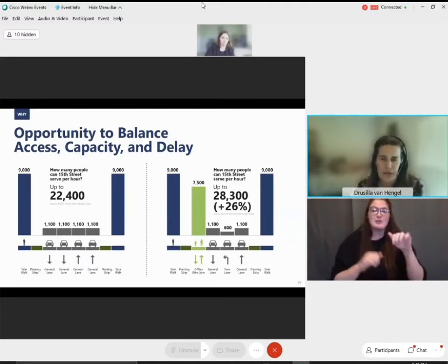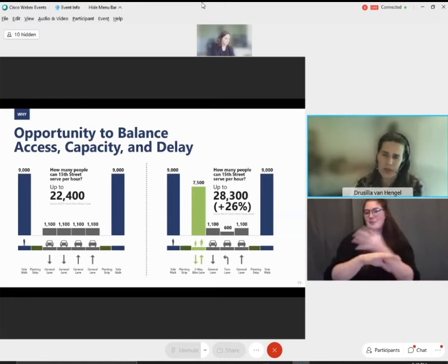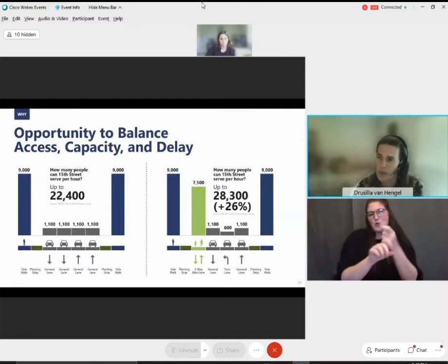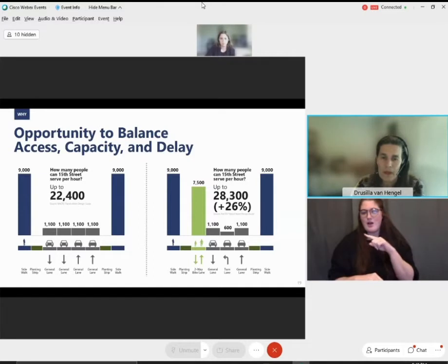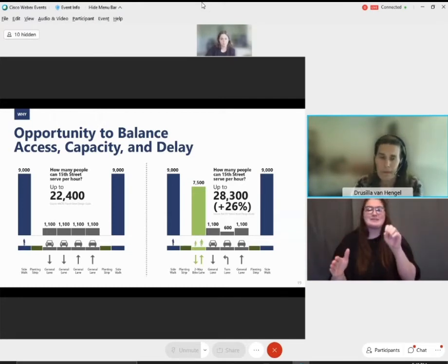But that said, there's a clear consensus developing that a significant portion of office workers will continue full-time or part-time work from home status. So our projection of delay is conservative and reflects a probable worst case. The range of passenger car delay along intersections today ranges from 2 seconds to 56 seconds. And the future average delay is expected to range from 4 seconds to 103 seconds under the proposed designs, which we'll talk about more later.